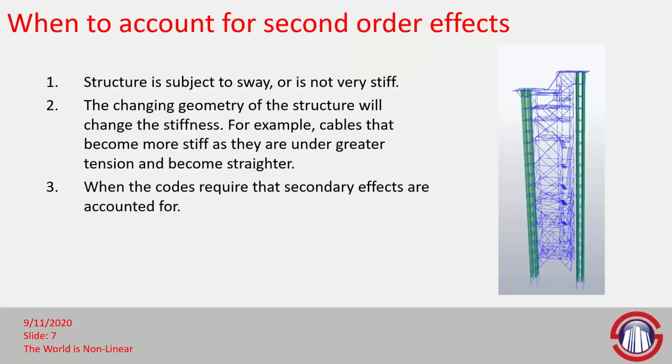Now, design codes may also describe when you would need to use second order analysis, and that's one that requires perhaps a little bit less judgment on your part since it's spelled out for you in the design codes.